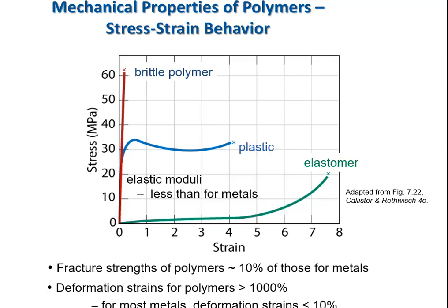And we will go over that specifically with an exercise in polymer behavior, one of your class exercises, I believe. Elastomers, again, behave sort of like the last portion of your thermoplastic, plasticized, your blue curve, your non-brittle polymers. You'll have very large strains, low stresses, and then the stress rising only at the very end, right before failure. And that's usually due to chain alignment. Elastomers tend to coil around one another in a fairly regular pattern.